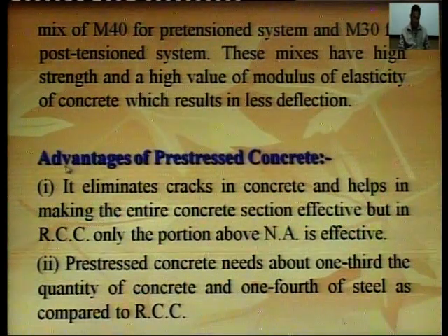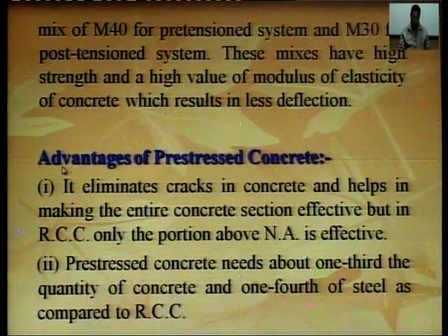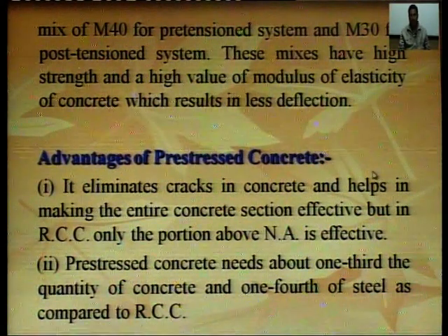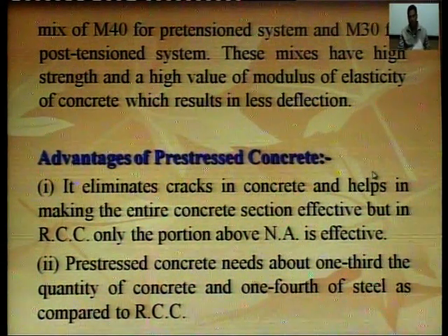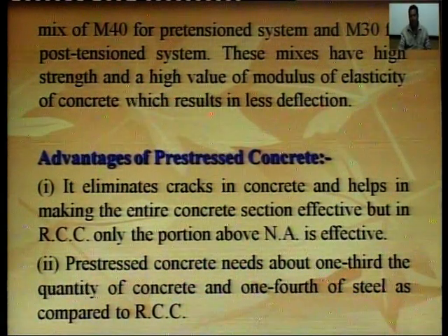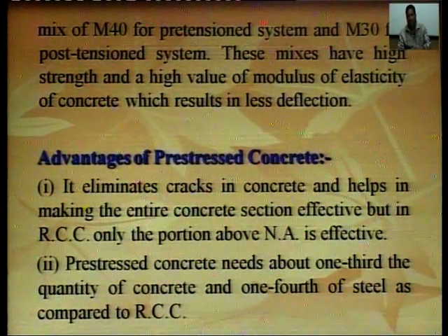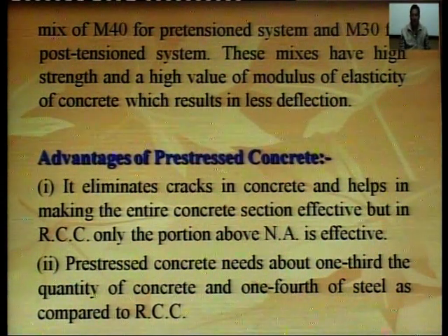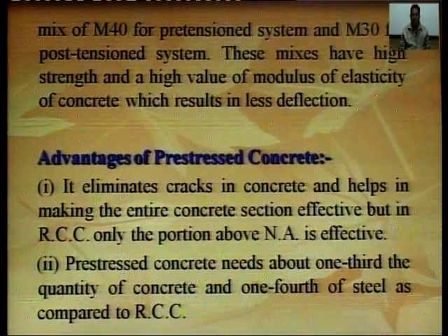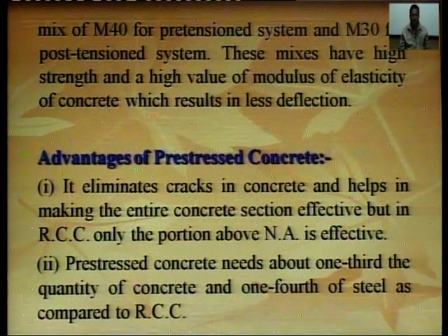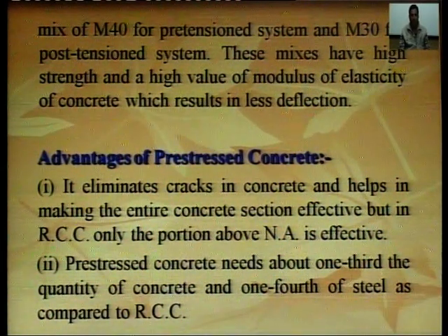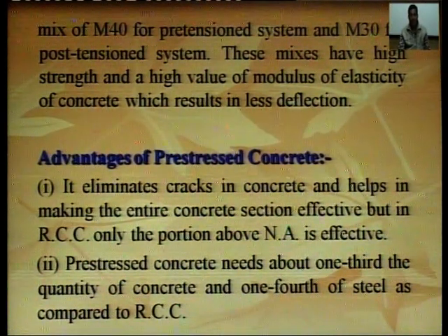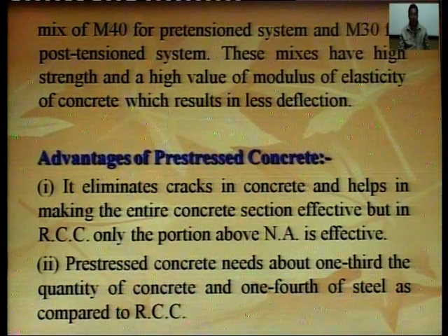Next topic is the advantages of pre-stressed concrete. What are the various advantages of pre-stressed concrete? It eliminates cracks and helps in making the entire concrete section effective, but in RCC only the portion below the neutral axis is effective. In RCC, the neutral axis divides the section into two halves.